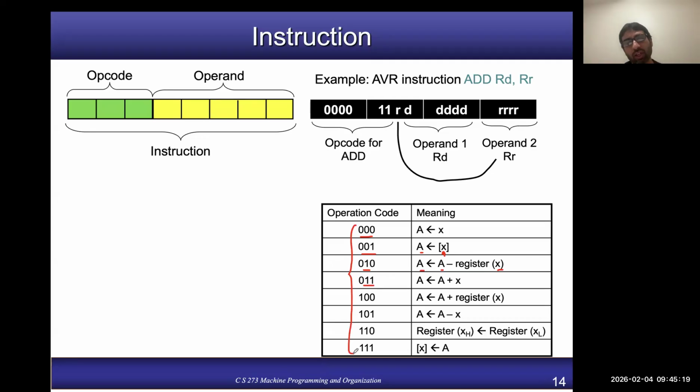For example, if you are building your own microcontroller, and in that microcontroller you have to design an instruction decoder, you need to use the opcode. So this is one possible 3-bit encoding, and you say, okay, I will always have a 3-bit opcode. So you can support 8 different operations, by reserving one bit pattern for one particular operation.